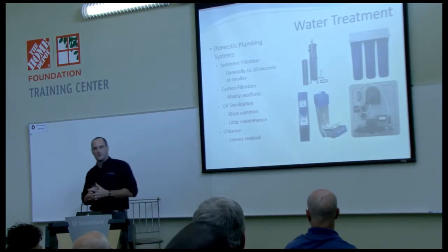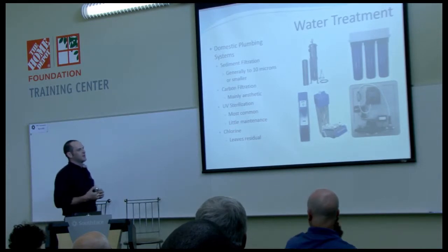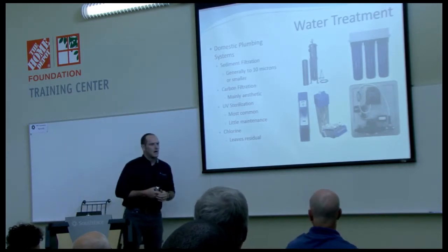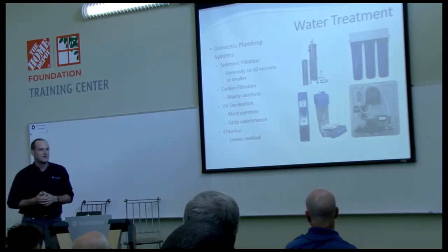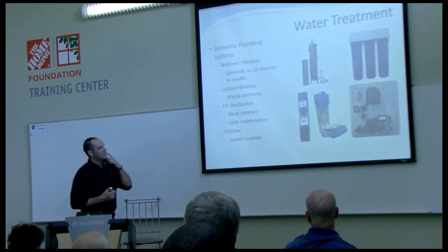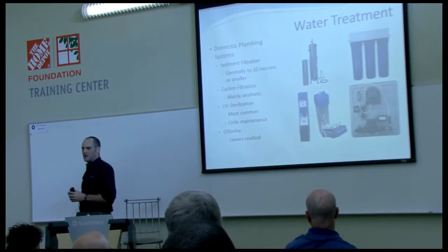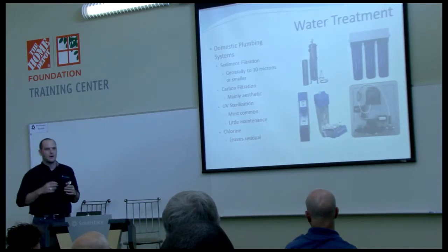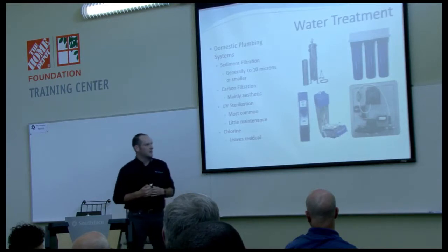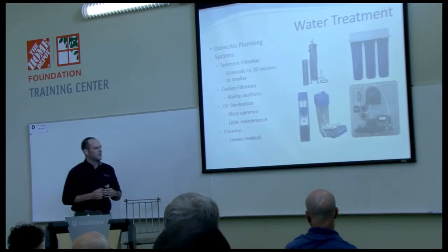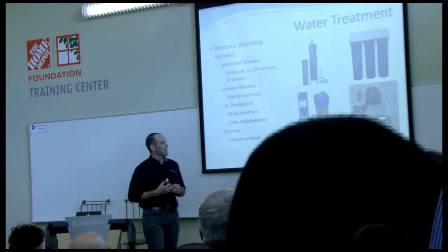Water treatment. A lot of these systems that we've done have been used for toilet flushing, and some of them even potable systems. Per code here in Atlanta, if you're going to bring the water back in the house, it needs to be disinfected. The most common way we see that being done is with sediment filtration and UV sterilization. A UV sterilizer basically exposes the water to a dose of UV light that renders anything, viruses, bacteria, things like that in the water, unable to reproduce. It actually doesn't kill anything, it sterilizes it in that fashion.